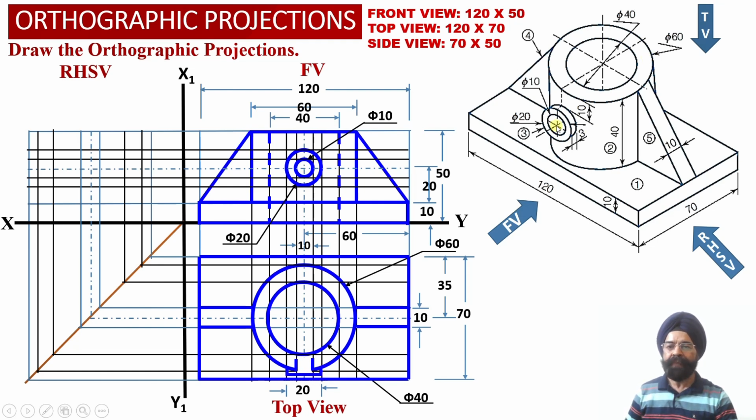And now we can check, as we are going to add a snug through this hollow part over here, there will be a hole in this short cylinder. So here we have got a hollow cylinder. Because this hollow part of the cylinder will not be visible to the observer from the top, this hollow part will have a diameter equal to 10 millimeter. Corresponding to this hollow part, we have been able to obtain hidden line projections into the top view projections over here.